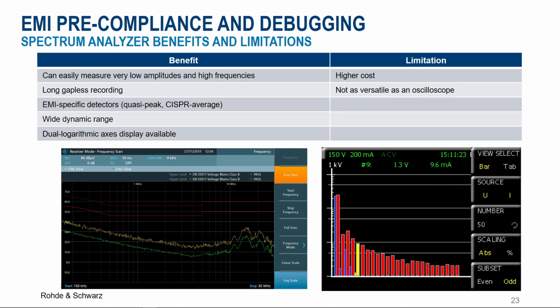Radiated emissions are inherent to any electrical circuit. A spectrum analyzer is an excellent tool for designers to measure the electromagnetic field strength of unintentional emissions generated by your products. A standard requirement for power quality includes testing for harmonics. Unwanted harmonics increase the heat generated in the electrical system, leading to losses, greater costs, as well as reduced performance of the system itself. Limiting the harmonics is an important task.